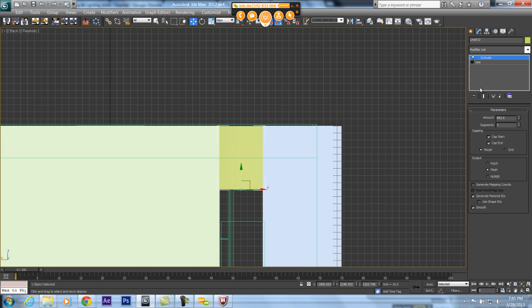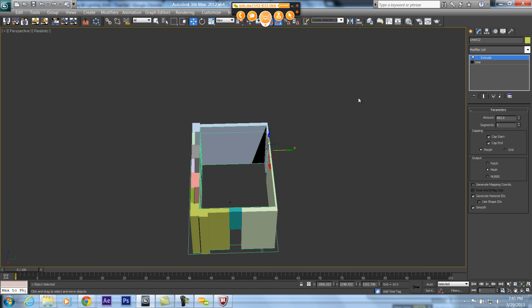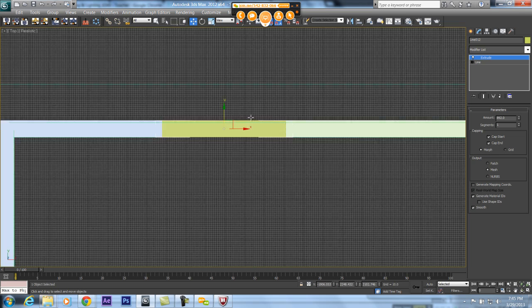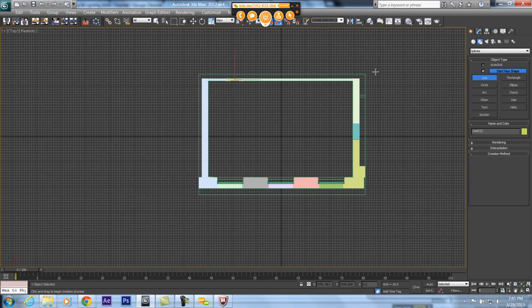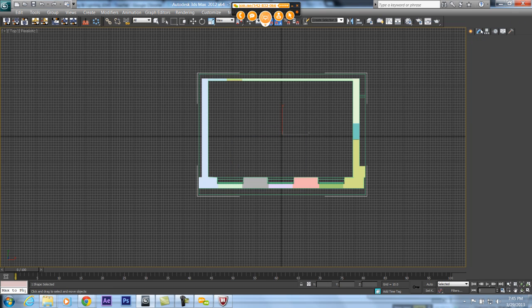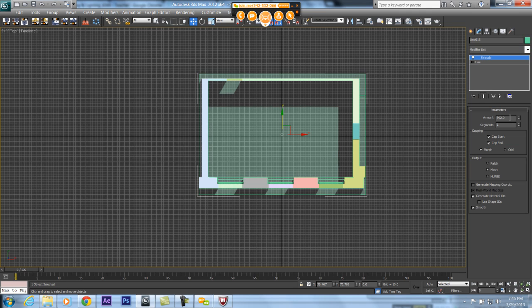It's very important to know all the hotkeys in order to have a really fast workflow. So I'm going to press P again, and voila, I have made my room. The only thing missing is the floor. So same here, I'm going to go through the line and make the floor. With the floor, I always try to go in minus when I'm adding extrude, because I want to go from the level 0 down. So I'm going to add extrude and I'm going to do minus 50.